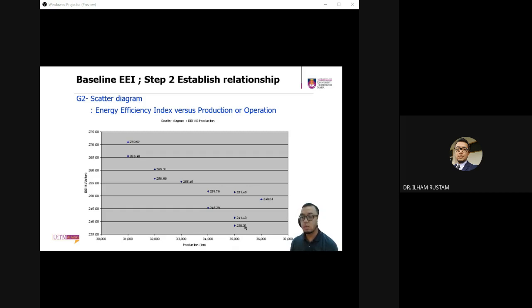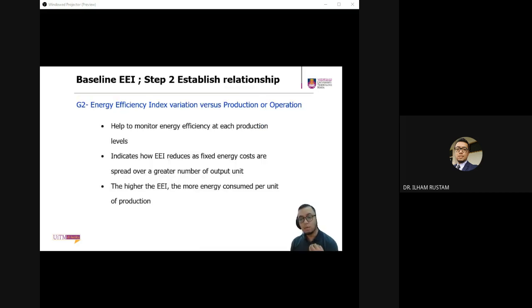So in some cases, if you buy the most expensive machine, most probably boleh handle lah. But again, depend on the machine itself. If you want the machine to run a marathon instead of sprinting because you want it to last longer, don't push 35,000, push 34,000, for example. Make sure it's around 33 or 34,000. Then the machine, you can strike a balance between working hard and also having a quality of life for the machine. That means you don't have to do maintenance that much. You don't have to shut it down so much for checking or for whatever example lah. While also be profitable. So again, cerita dia bukan grey, bukan black and white.